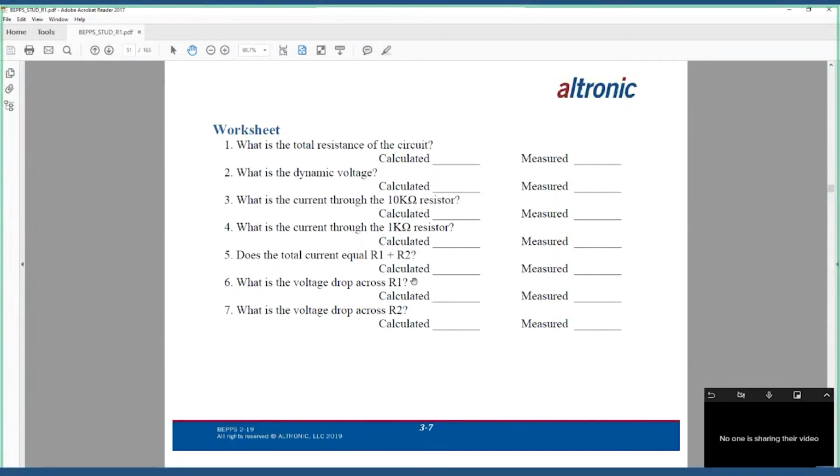We would see that our numbers aren't matching up with what we're actually measuring. So we know that our total resistance is 909. So actually, we take 909 for our total circuit resistance and we work the same formula. Let's see if I can help fill in the piece here.